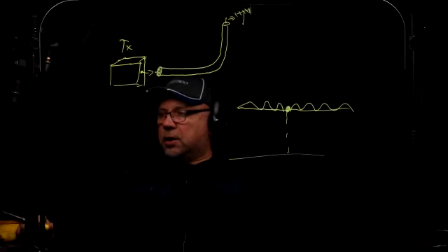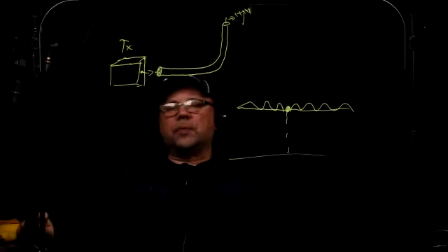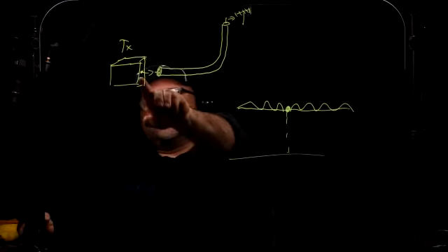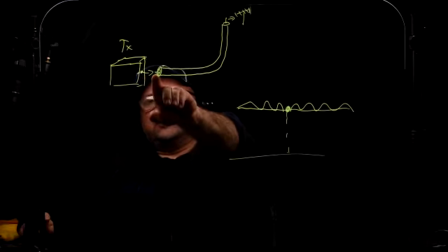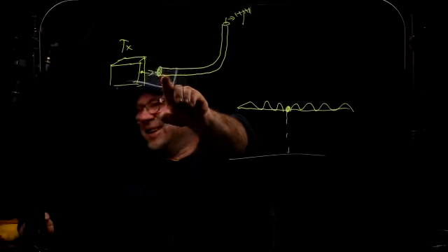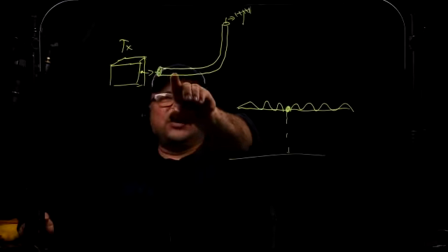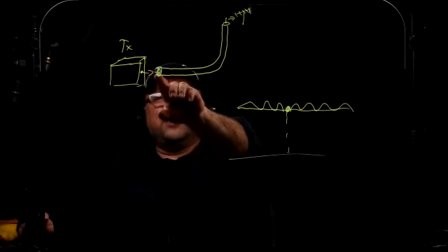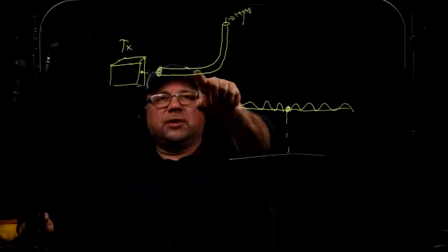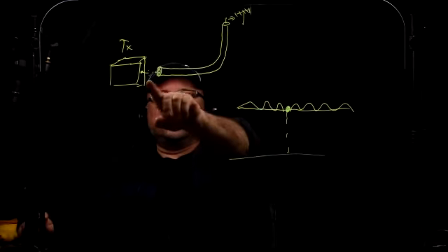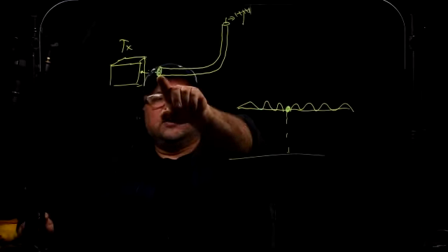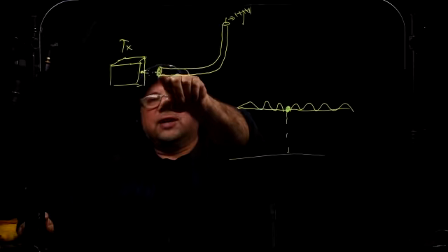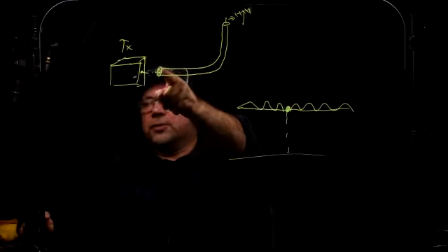However, the answer is no. Because the transmitter only cares about how difficult it is to insert the wave into that cable, and then the wave continues on its own. It's just creating a wave, and now we can disconnect, and the wave is going to continue by itself. So the characteristic impedance is the impedance based on the capacitance of the entrance, only the entrance.